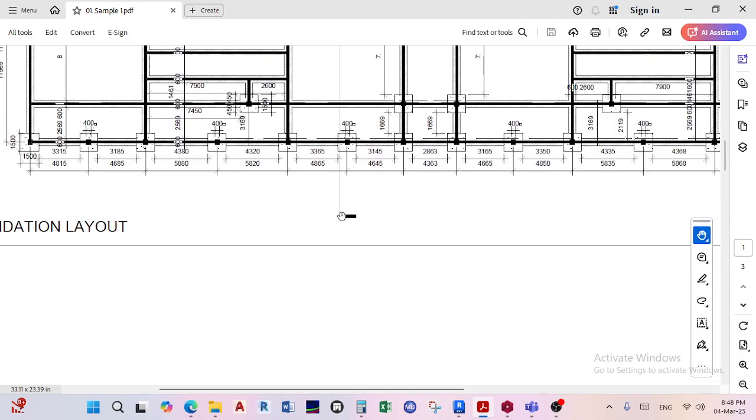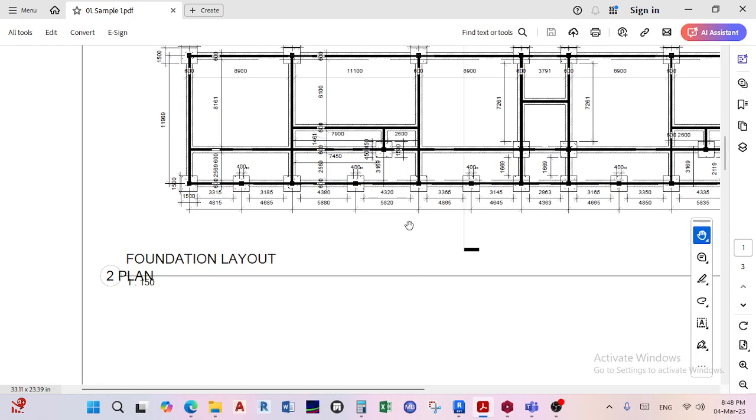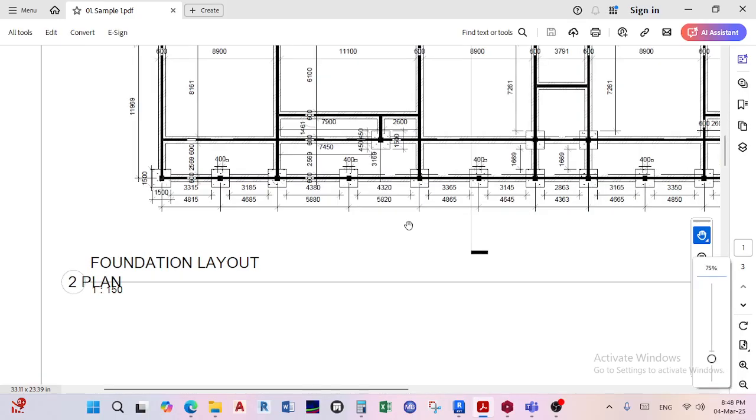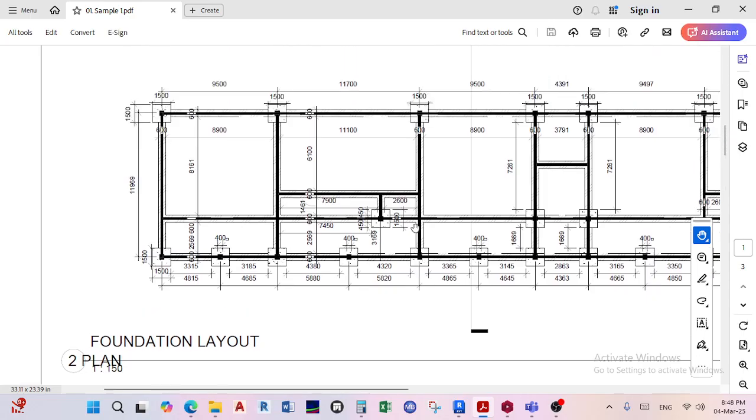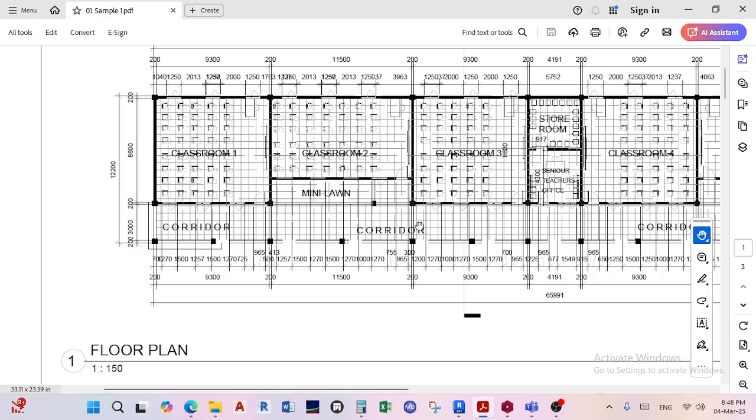So now suppose you're a structural engineer, especially if you've got a structural engineering background, the first thing that will come to your mind is, okay, you're trying to add another floor or another level. Is what you've designed, especially the foundations, the columns and the beams, going to be sufficient to support more loading? Because if this is a classroom block, then you're going to have some dead loads from the concrete itself when it dries, about 2.8 if I'm not mistaken.